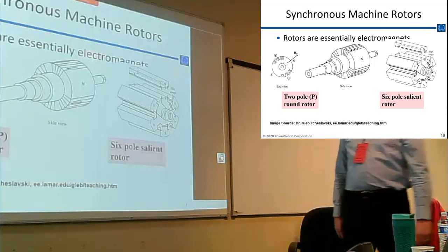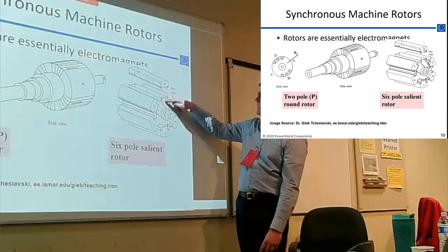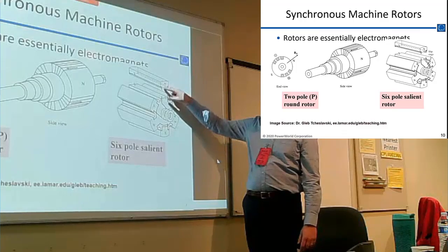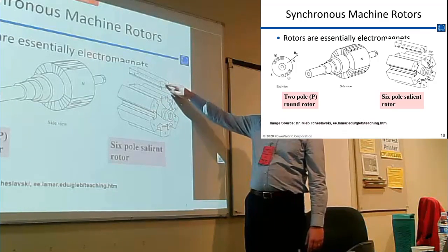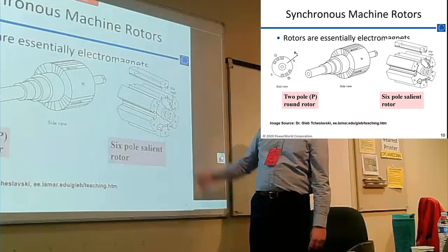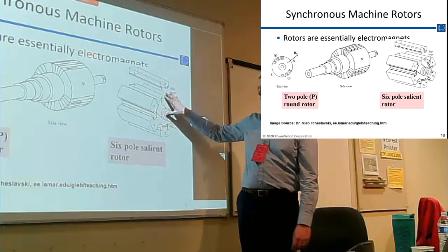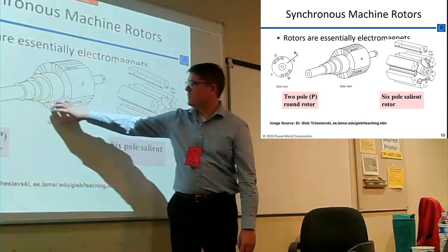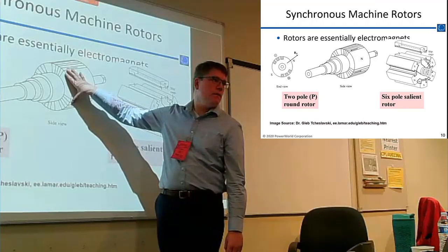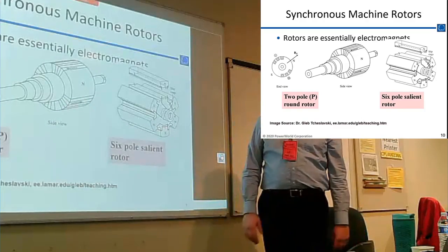Synchronous machine rotors, you can design them like this. There's the slip rings, and you're talking about a keyway, spider. The pole pieces, you call them? Okay. So the top part would be a pole piece, and it would slide into the spider. We call the thing that has the little things that slide, pole piece slide. Okay. So this is for a salient rotor, and this would be more where you've got the windings in here. Actually, I think this is meant to represent a permanent magnet rotor, where these pieces are actual magnets. But anyway, there's different ways to actually build the rotor itself.